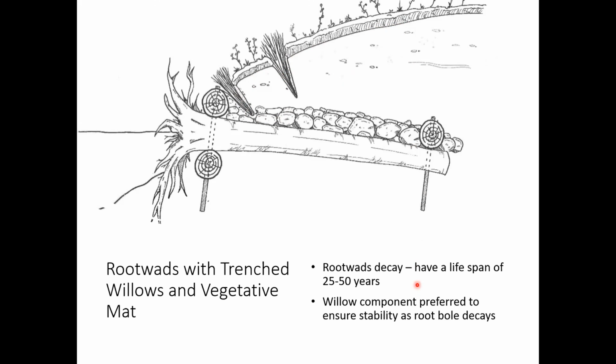Yep. And yeah, their root wads are still holding. They look excellent. They're still doing the job that they were hoping it would do. And yeah, willow is excellent to put on here because as your root fans and root wads start to break down, hopefully by that point your willow stems will have grown and you'll have robust willows that'll hold the soil in place.